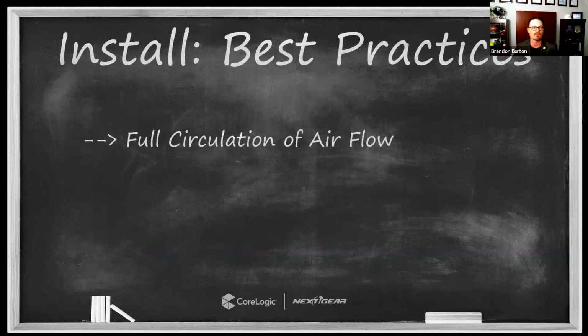All right, so installation best practices. Quick review of some of those best practices. First of all, the goal here is to get full circulation of airflow onto and across all wet evaporating surfaces. That's the goal, right? I gave you 2 ways to verify that, as simple as using your hand to feel that sensible cooling from that air moving across it. If you want to be more precise or give yourself some really good documentation, then use your thermal hygrometer at that surface, especially in higher value surface materials or projects where we're dealing with higher value goods. It'll be worth that time and energy to take some of those measurements.